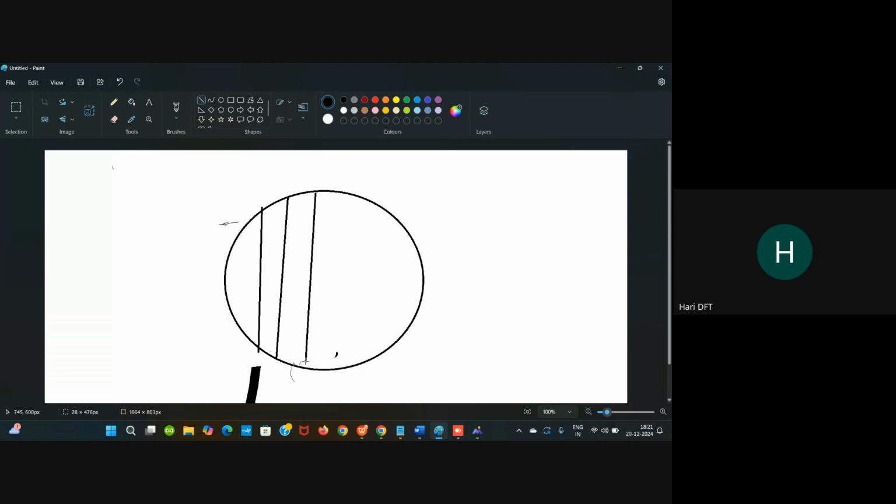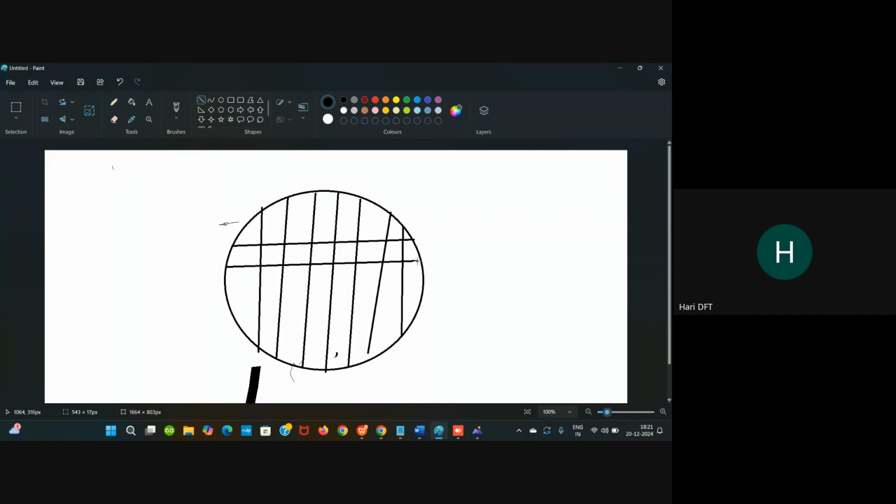This is how a die looks like. The entire unit is called a wafer, and we will be having dies on it, I mean, replicas of a single design. When we tape out a single design, it will be replicated multiple times like this. Each unit is called a die.